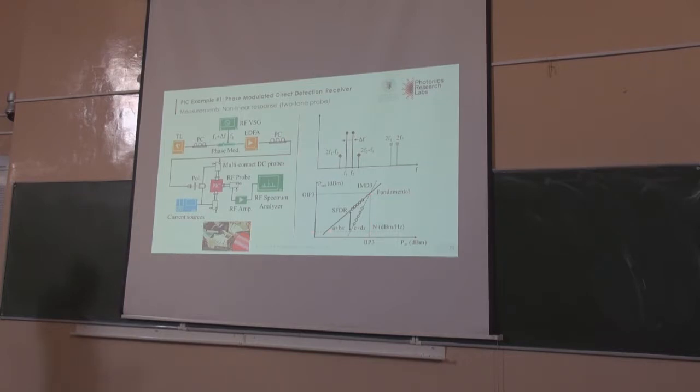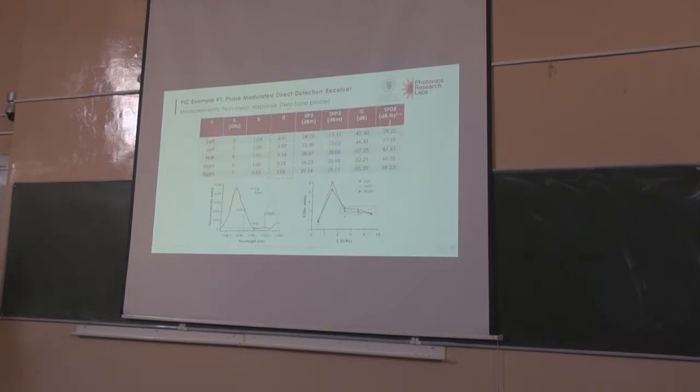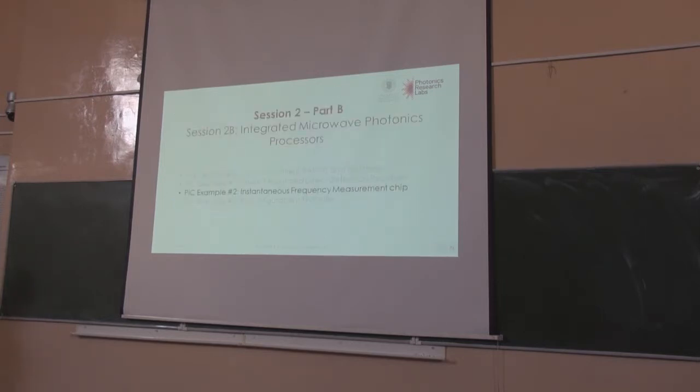The spurious-free dynamic range is the range in dB where you don't have any spurious tones, okay? Where your system is to be considered linear. This is the base noise, and this is the spurious-free dynamic range. I'll skip this one and this one, okay? Any question on the frequency discrimination?